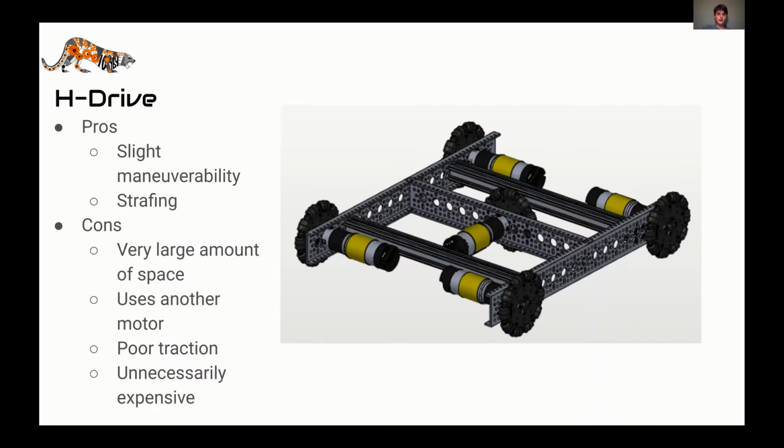But it is easier to program than something like a mecanum drive or even an X drive. But it's just things to consider. It also takes up a lot of your building space right in the center of your robot where you just can't put anything there because it's being used up. And it has about the same traction as that 4-wheel Omni drive that we were talking about earlier and the X drive, which isn't great, but isn't too terrible either.